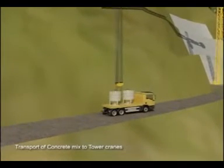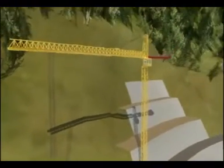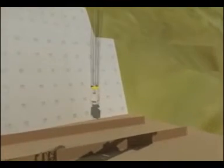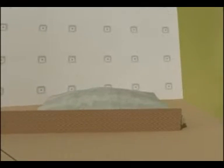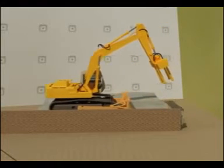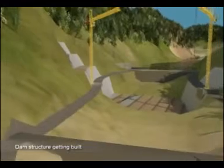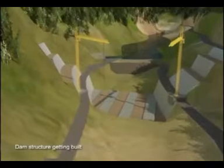The crane keeps down an empty bucket, picks up the loaded one, and delivers the concrete to the desired location of the concrete fill that is demarcated by steel shuttering. A concrete vibrator is used to ensure that the pour is even and free of air bubbles. Concrete is placed in layers of about 300 mm thickness along the block width in a 3-meter layer at a time so that cold joints during placement are avoided.